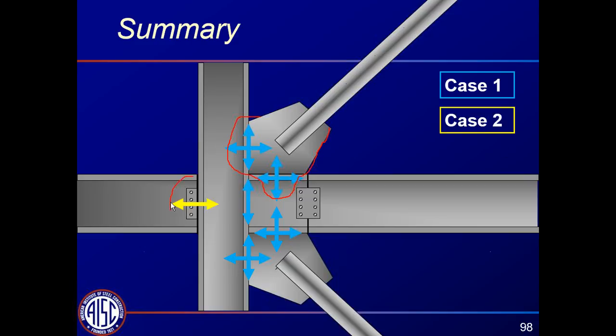really only tells us the maximum force outside of the braced frame. The mechanism forces are going to govern within the braced frame. And here's case 3, and that tells us the maximum horizontal force in this joint and the maximum horizontal force in this joint. So really we couldn't design this connection adequately without looking at 3 different cases.